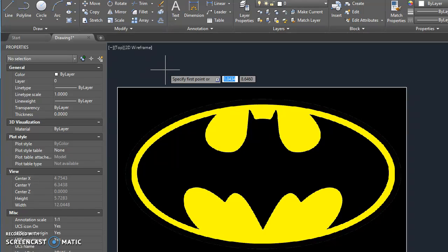Spline is a curved line, but for this assignment, the one thing you need to be cognizant about is that this entire thing has to be fully enclosed. I'm clicking along my edge, so you do this also. With this spline, once you get to the end, you just press enter and you're done. Do not loop it around because then it's going to make a big arc right here.